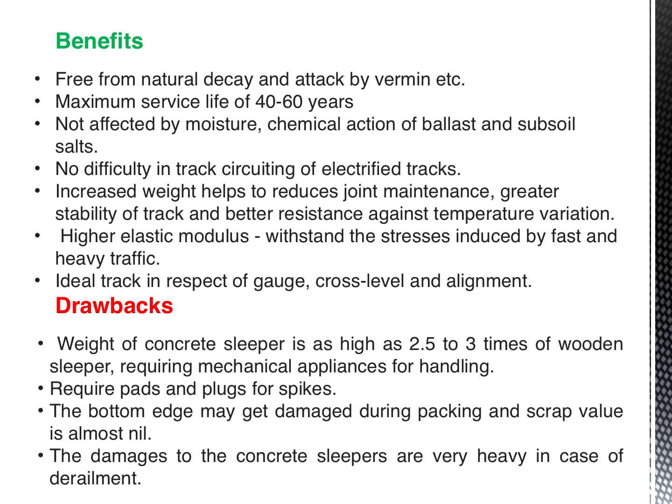Also, the increased weight of the concrete sleeper reduces joint maintenance, and the track will have greater stability and better resistance against temperature variations. Concrete sleepers have a higher elastic modulus, and hence can withstand the stresses induced by fast and heavy traffic. It is also an ideal track with respect to the maintenance of the gauge, cross level, and alignment. But the drawback here, the weight, is one of the major drawbacks.